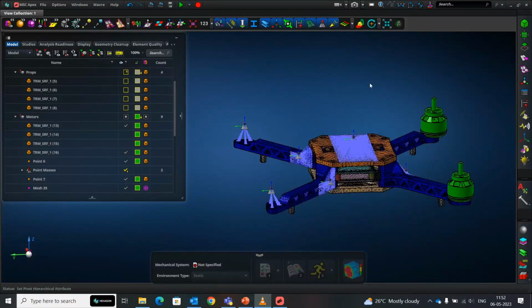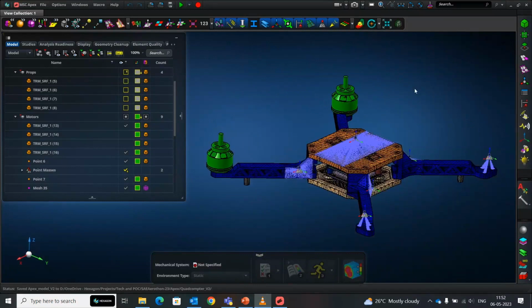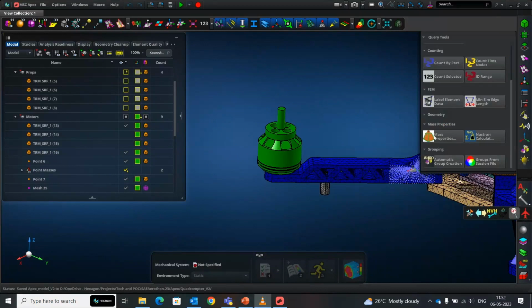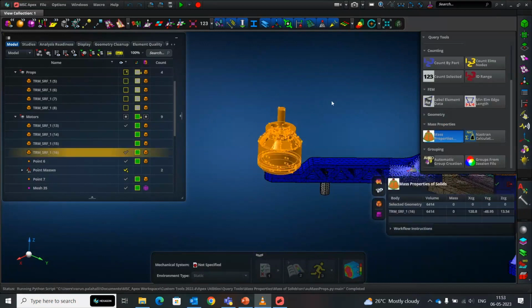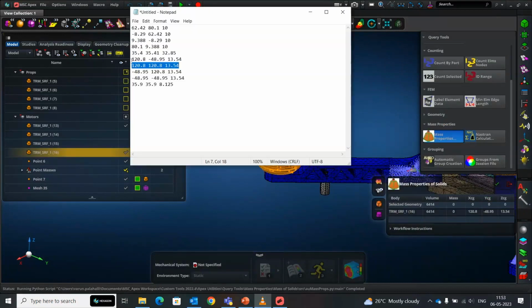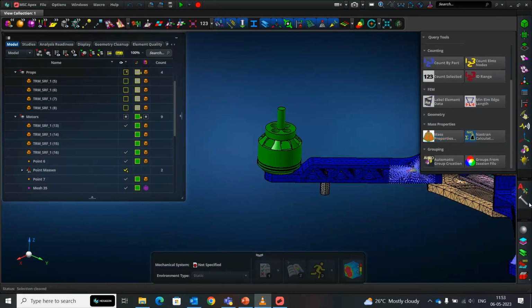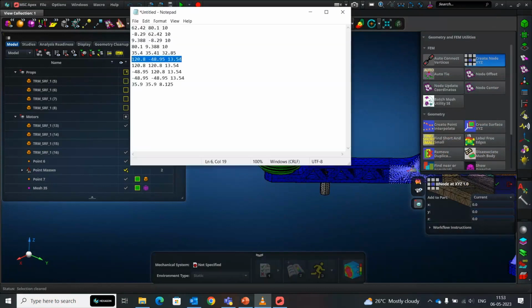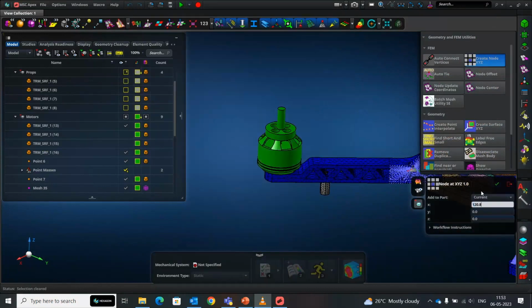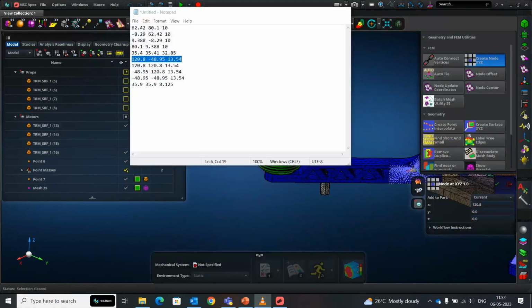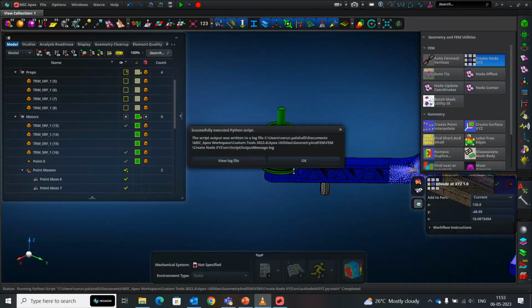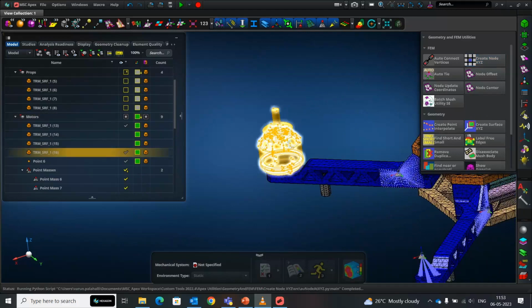Please do bear with me for this. I go to the query tool. I want to find what my CG of this is. The only thing that will vary is my ZCG. So I know the CG location, and then create a node corresponding to that CG location. Once again, take the cumulative CG location of the Z, and then I've created a node.